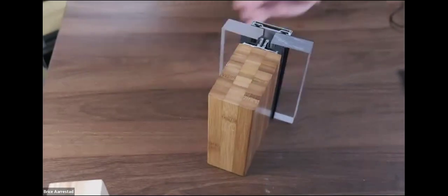And what I think is unique about these systems, or one thing to keep in mind, is that when it comes to any sort of curtain wall and any sort of material that is supposed to be bracing against the wind, you want to know how each of those components in that system function and how they'll perform given wind loads, given gravity loads, and other loads that might be attached to this system. So we can't use just heavy timbers because they twist, they move, they crack, they separate. We can't use stock 2x4s or 2x materials. We have to use an engineered wood. So most times it's a glulam.